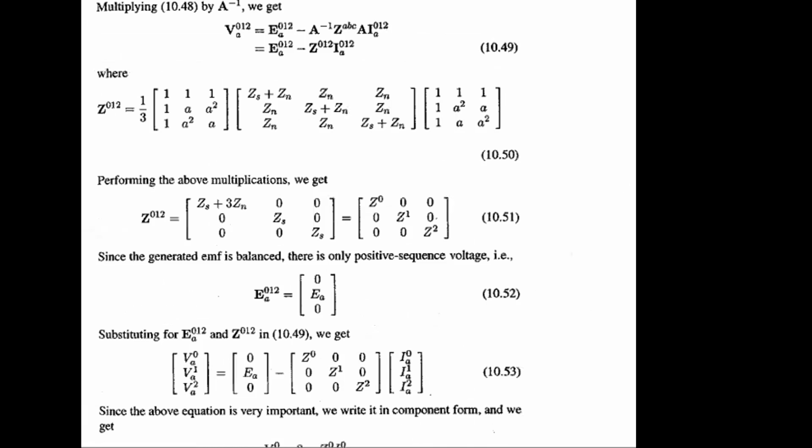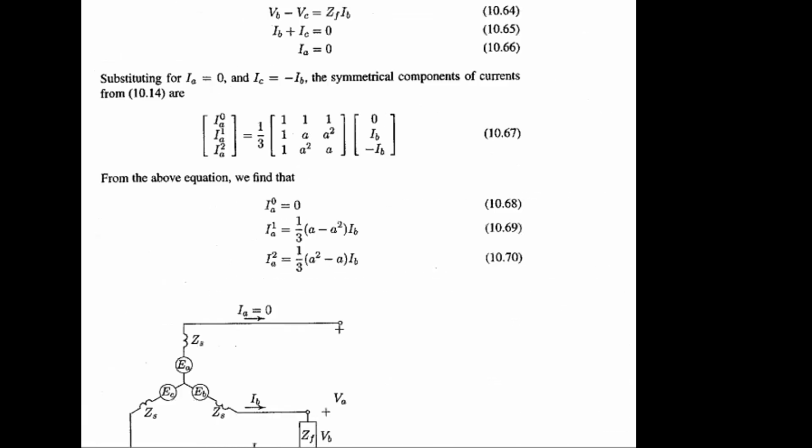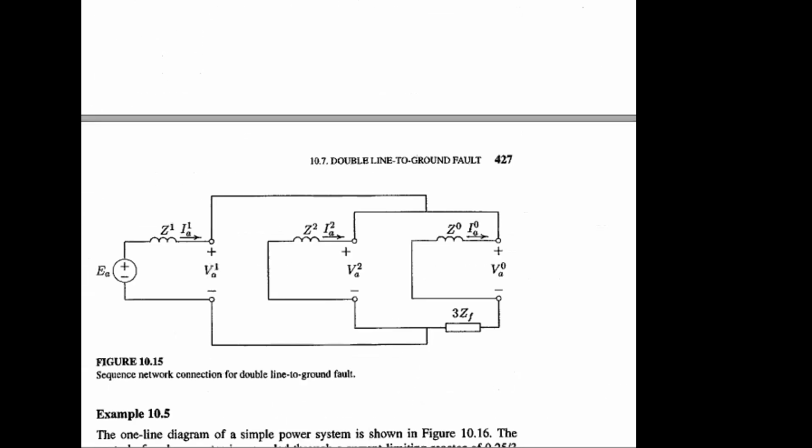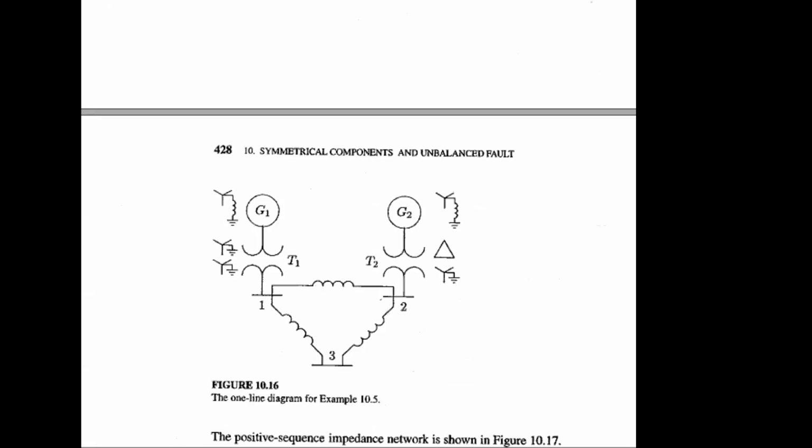The different configurations for the transformer zero sequence circuit. Yeah. Here we started the journey, right? Here you can see transformer T1 has both sides grounded, right? But transformer T2 will have delta and Y. So you have to draw the zero sequence circuit accordingly.